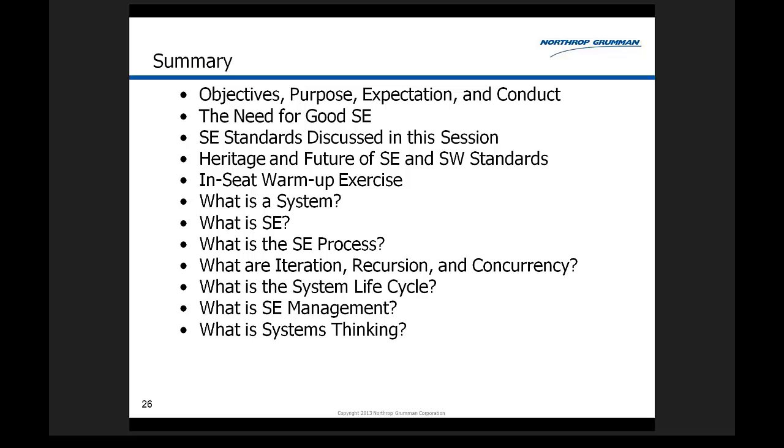My knowledge of CORE is that it's the most comprehensive and the most complete tool. It's a full-featured tool that allows you to create a model of the system in the tool and exercise the model, both verify that the requirements are met by the functions, exercise the functions, and they're allocated to elements, and do timing studies and optimize the allocations of requirements to functions and elements.